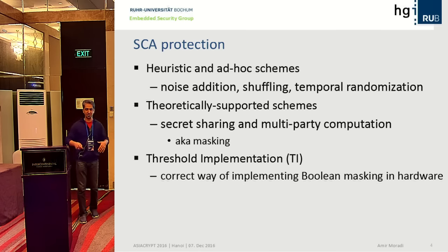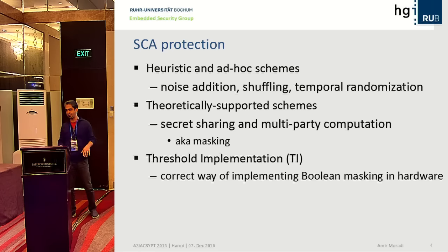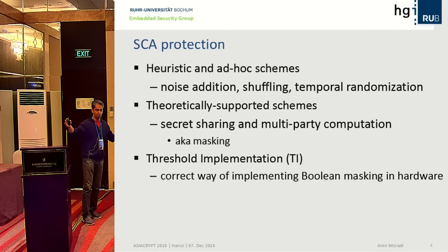Of course, it increases the noise, and then the attacker has a bit more difficulty performing the attack, depending on the level of noise that you add. Shuffling most likely is not possible here, because you don't have any register, you don't have any order of the computations. This is just a fully combinatorial circuit, and you have no chance to change the temporal order of the operations, the same for temporal randomization.